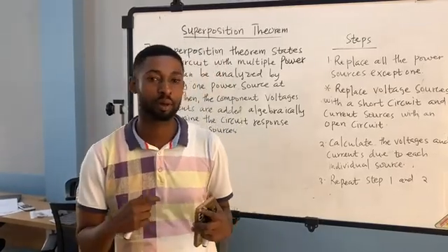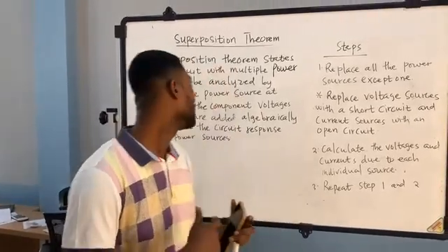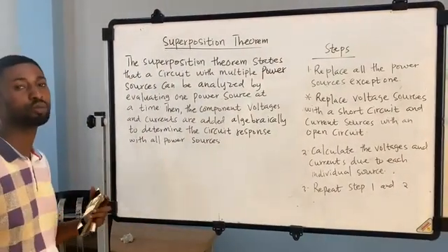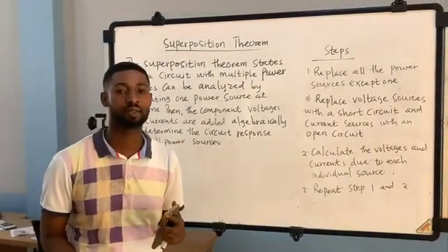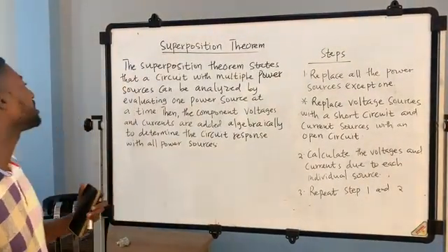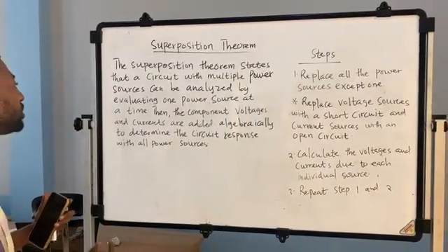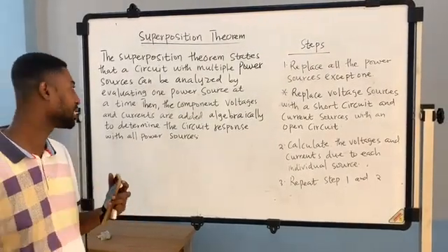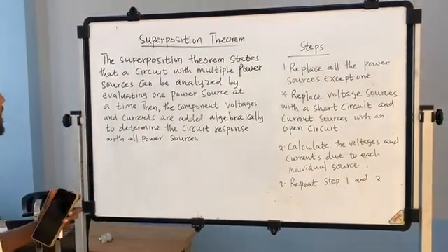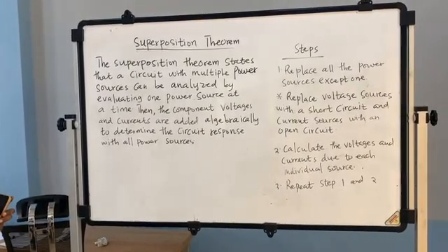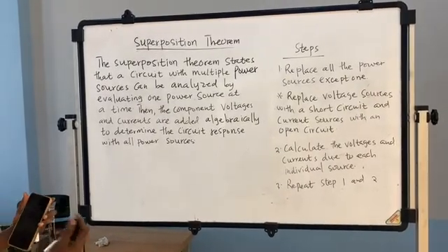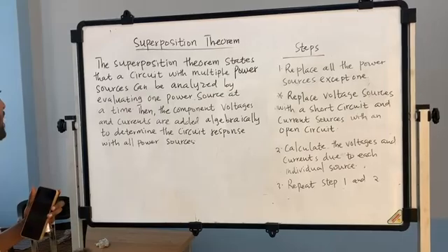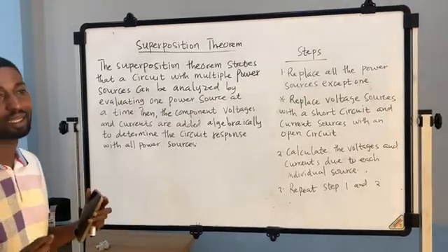In today's lesson, we are going to talk about superposition. Superposition is also a theorem used to simplify circuits. The superposition theorem states that a circuit with multiple power sources can be analyzed by evaluating one power source at a time.